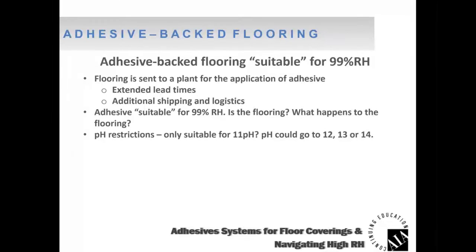If the adhesive is only suitable for a certain pH and we get to condensed liquid, the pH could go to 12, 13, 14. If we're outside of the pH recommendations and there's an issue, then the manufacturer is going to say, hey, the pH has exceeded our maximum. So look at the pH and understand any limitations associated with pH.